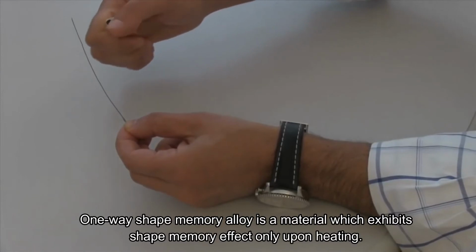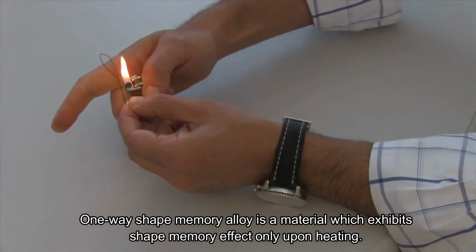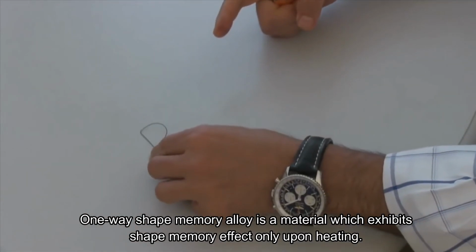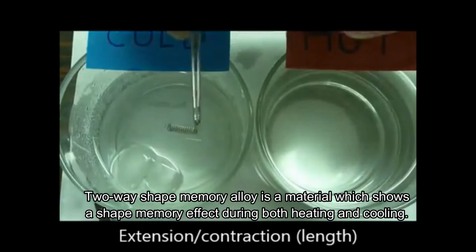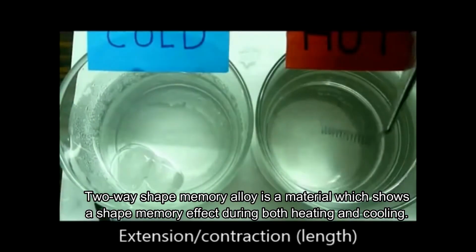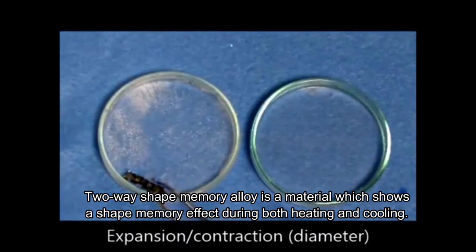There are two types of shape memory alloy. Firstly is one-way shape memory alloy. One-way shape memory alloy is a material which exhibits the shape memory effect only upon heating. And then two-way shape memory alloy. Two-way shape memory alloy is a material which shows a shape memory effect during both heating and cooling.